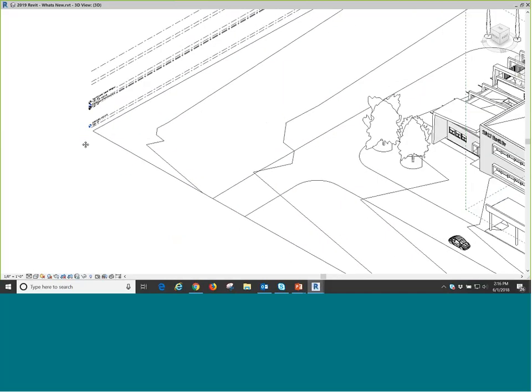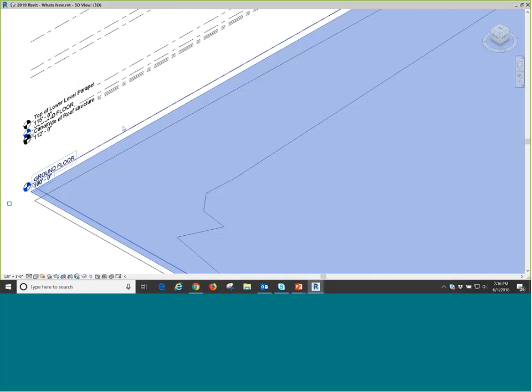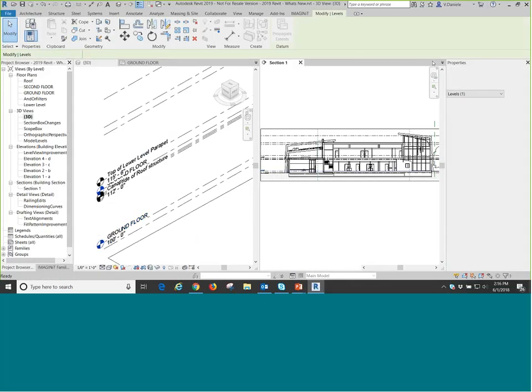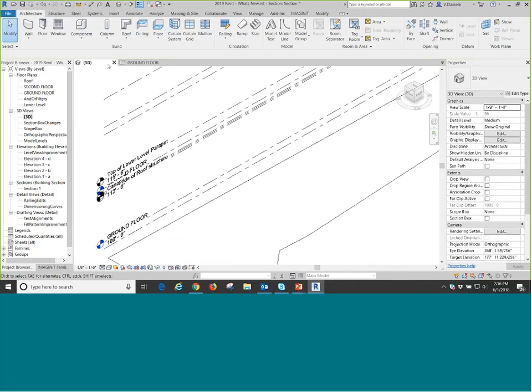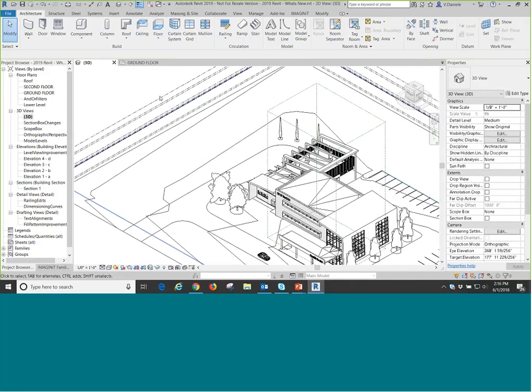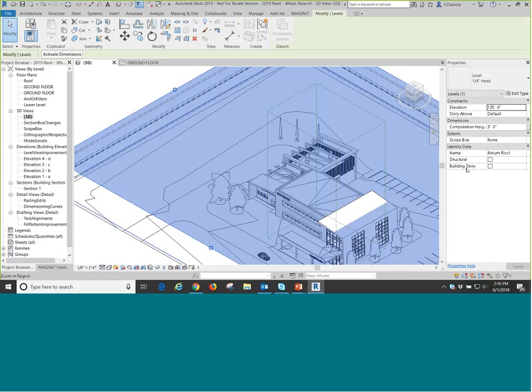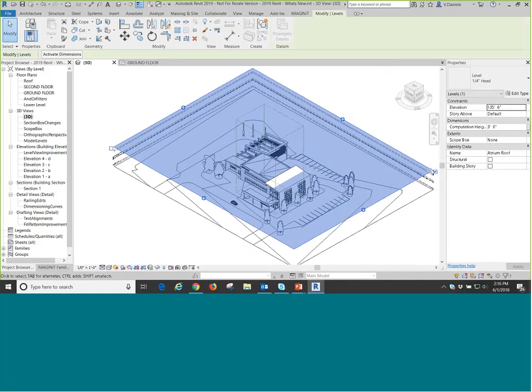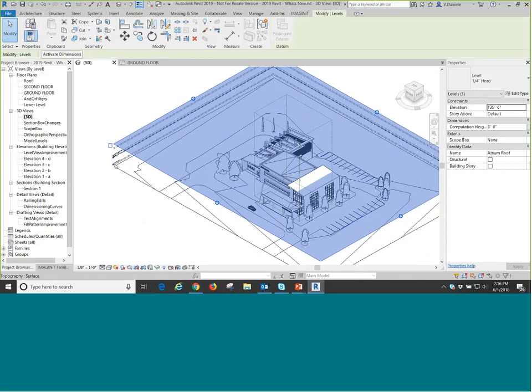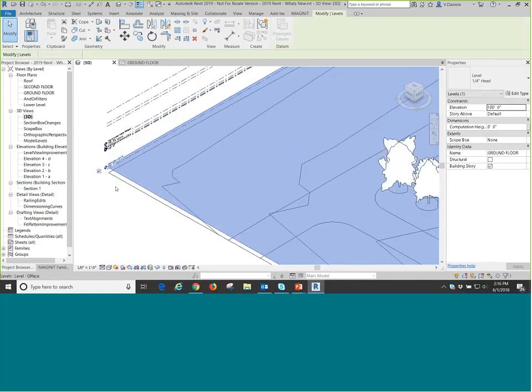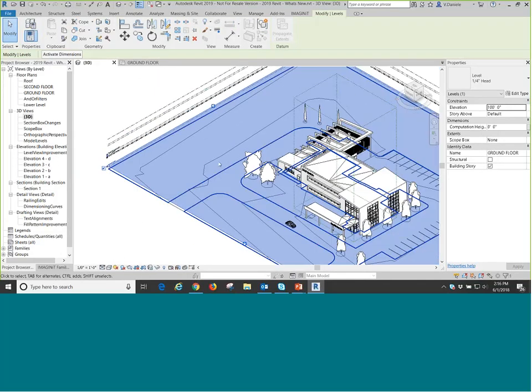But as you can see here, in the 3D view, we can select levels, we can edit level name, level information, and if I minimize this and dock it back to the main screen, sorry, I'm just getting used to this just like everyone else here. So you can click on a level and you can edit the properties on the fly while you're working in 3D views. Not a huge improvement, but hey, it was around in conceptual massing for a long time. Why not integrate it into our project workflows and have consistency between those environments.